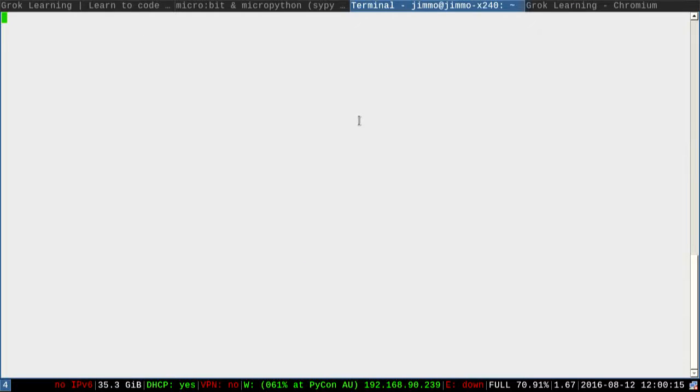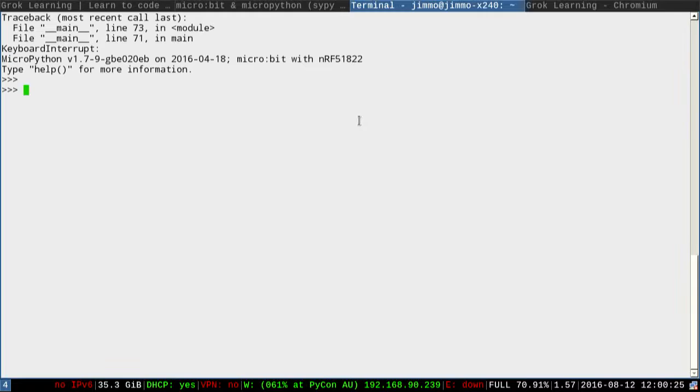I've actually yet to succeed at more than about once. But the great thing about this, and this is true of many MicroPython boards, is that I can connect to this as a terminal. At the moment my code's running, so I just see nothing on the terminal. But just like a regular Python program, I can hit Control-C, and here I am at the Python prompt. And this is the exciting part about MicroPython, something you just can't even imagine doing on an Arduino, is that I can run Python code on this board.